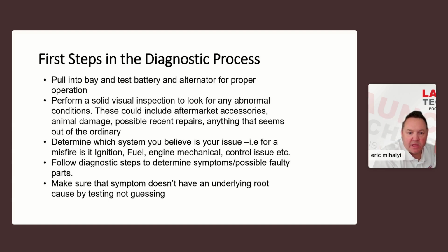So some of the symptoms with that could be network problems, because the network will start to shut down. AC ripple is noise in an electrical system, and it's like fingers on a chalkboard to the network. It just starts to shut the car down, right? So you'll have modules go silent and tune out. They're like, I'm done, I'm out, can't listen to this, right?